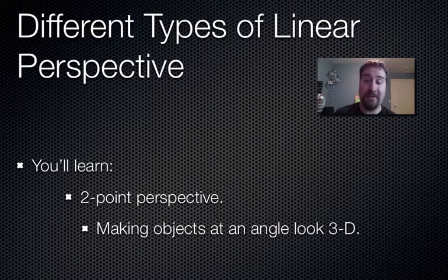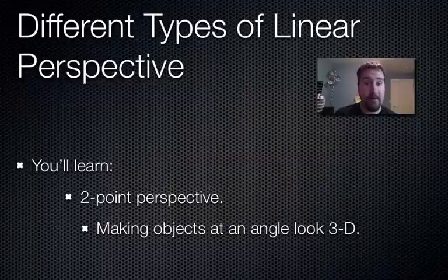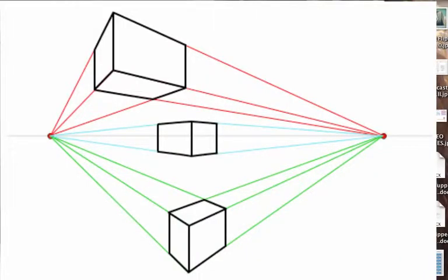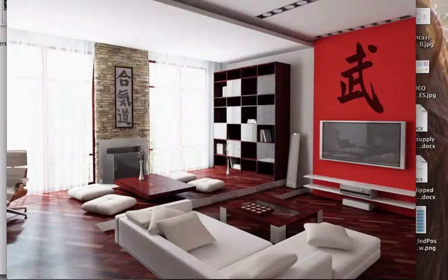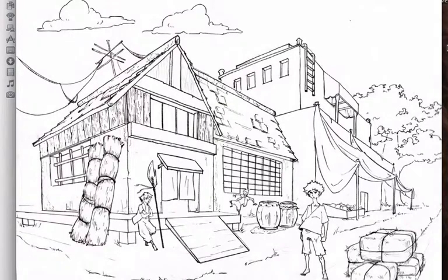You can see more sides of your subject than you could in one-point perspective, and therefore it's more believable. In two-point perspective, everything's at an angle. There are no flat edges facing you directly, only sharp corners. I find two-point perspective to be way easier than one-point perspective because it draws itself, in a sense. Also, the major difference in two-point perspective, no x-axis whatsoever. There are no left to right horizontal lines. There are simply vertical lines and slanted lines. That's it. And work in two-point perspective, again, it looks more realistic. You see more of your subject.